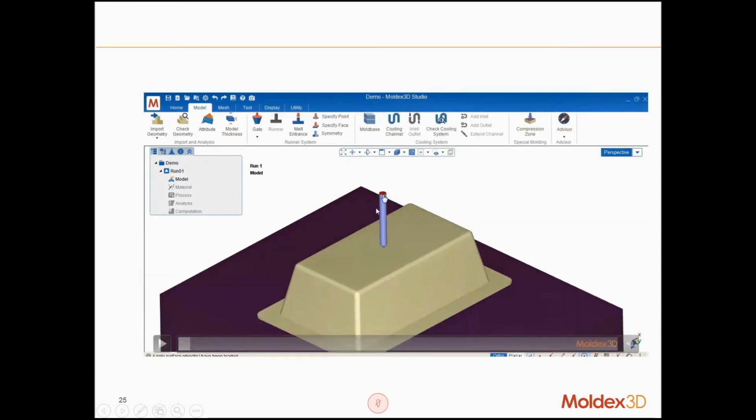I have a geometry runner, and I have a part, I have an insert, and in the past, sometimes there's a simulation problem because the resolution of the gate is too low, or the resolution at the sprue is too low, because we give the wrong mesh size. So personally, I recommend to do the node seeding separately. First, we do the node seeding for the runner.